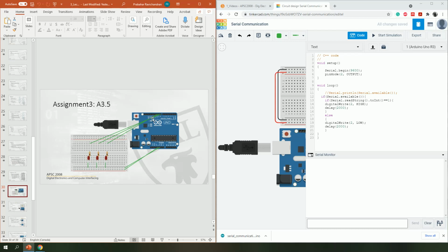You will have to set these 3 pins, you can use any of these pins, as output, and then in the loop you will have to read it using the same function we showed here, and then we will write based on the switch statement.